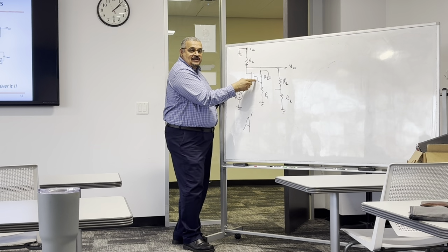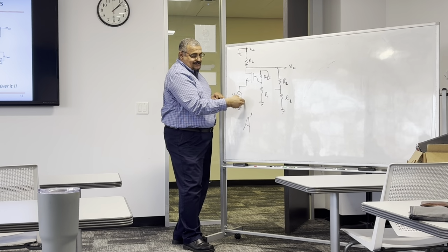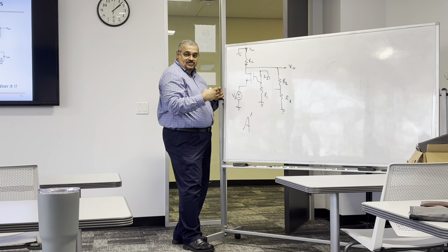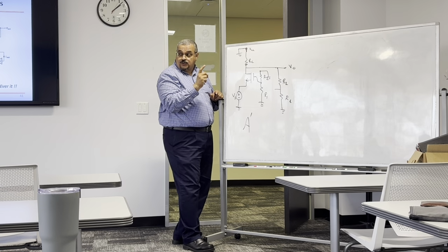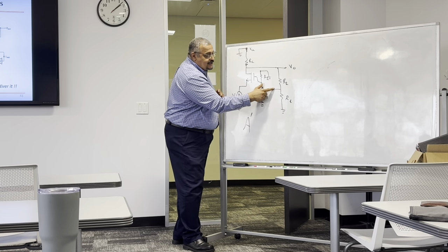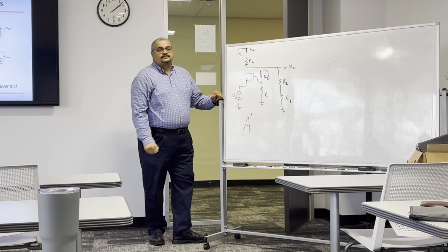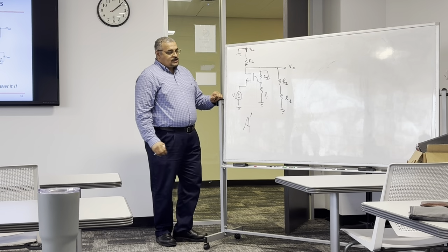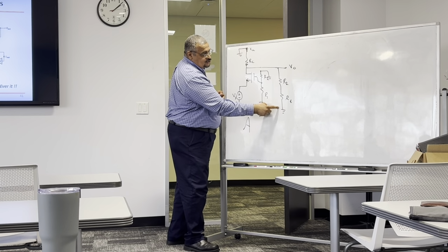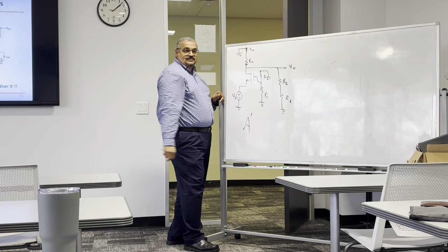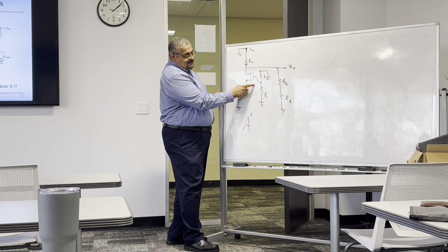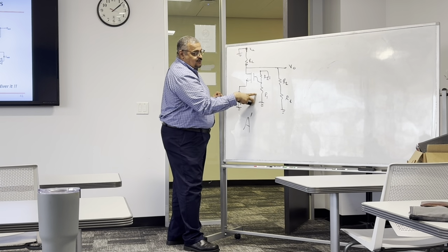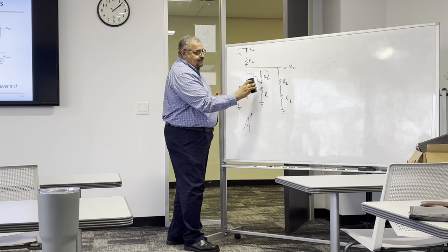This was connected here to do what? To mix a voltage, right? How do you mix voltage? Series or shunt? Series. Voltage, mixing, series. Then leave it open. So the effect of R1 and R2 at the output is in series. However, the effect at the input is R1 and R2 are going to be in parallel.